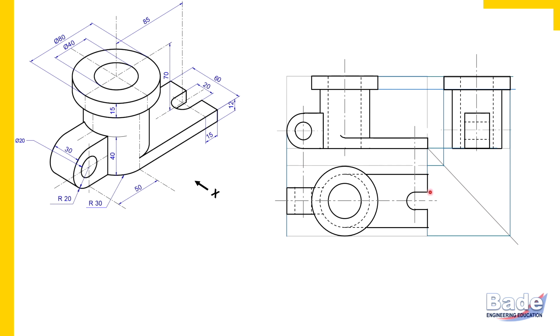Now draw end projectors. How are you going to draw the slot in the other two views? Rectangle between end projectors. Okay, so let's proceed. I have projected it, and this is how this rectangle here, that is the slot in the front view, which is hidden. And when I ask you where is this slot, don't just show me this dotted line. You must know that slot is present here. It's a complete rectangle here. This dotted line is only the boundary generator of this curved surface of the slot.